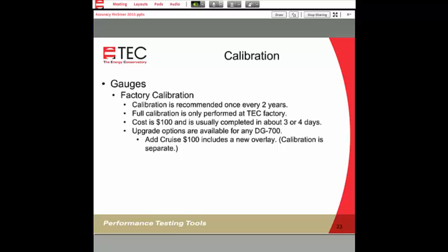If, when we see the as found data, it's 2, 3, 4% out of specification instead of within the 1%, then you might want to consider looking at all of the data that you've done recently and determine whether, given that we've measured it as 3% instead of 1, you need to go back to any of the other values that you've taken to make sure that you actually have done a worthwhile test.